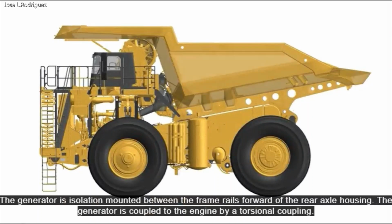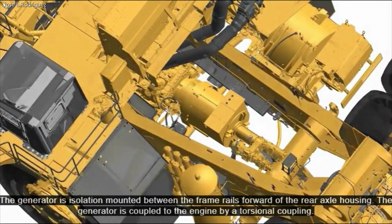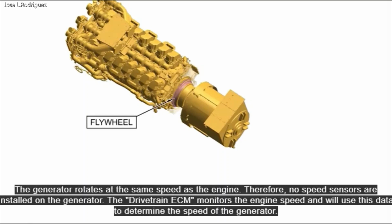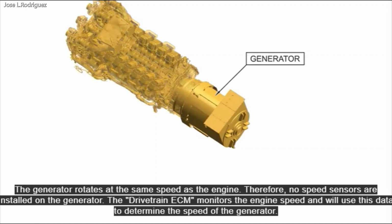The generator is isolation mounted between the frame rails forward of the rear axle housing. The generator is coupled to the engine by a torsional coupling. The generator rotates at the same speed as the engine. Therefore, no speed sensors are installed on the generator. The drivetrain ECM monitors the engine speed, and will use this data to determine the speed of the generator.